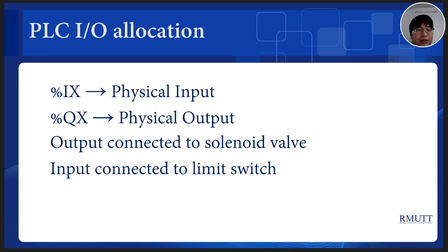This page shows the PLC input and output allocation. The physical inputs are set to %IX, and the physical outputs are assigned to %QX.